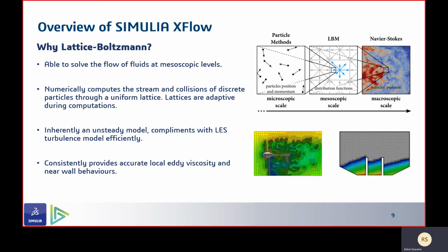which actually require constant communication with the LES turbulence model in order to compute the parameters they need to. So this actually takes computation time. Because of these, it's able to consistently provide accurate local eddy viscosities and near wall behaviors as well. As you can see with the images on your right, the mesh is highly refined to follow the wakes and to refine especially at those wake regions and the boundaries of the geometry.